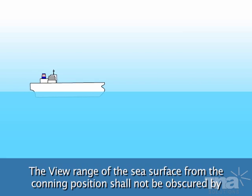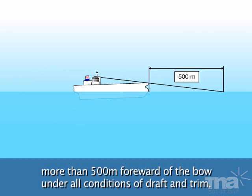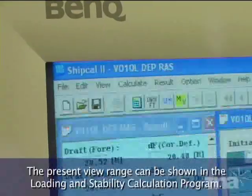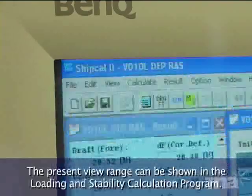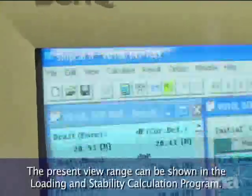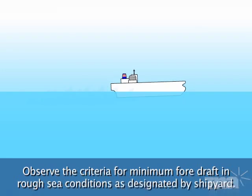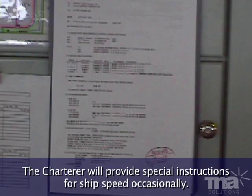The view range of the sea surface from the conning position shall not be obscured by more than 500 meters forward of the bow under all conditions of draft and trim. The present view range can be shown in the loading and stability calculation program. Observe the criteria for minimum foredraft in rough sea conditions as designated by shipyard. The charterer will provide special instructions for ship speed occasionally.